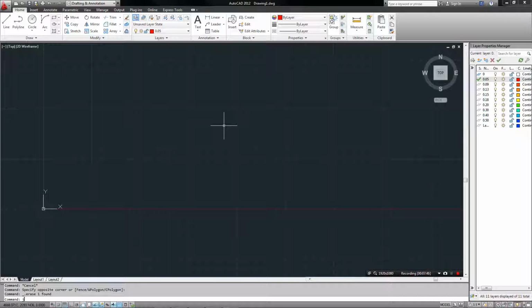Now the Fillet tool. So I've got two lines converging at a point. If I press F, fillet, and select the lines I want to fillet, it's going to cut them nice and small, and it's going to do it at a right angle unless I put in a radius. So let's do that again. Got my lines selected, we've got fillet.